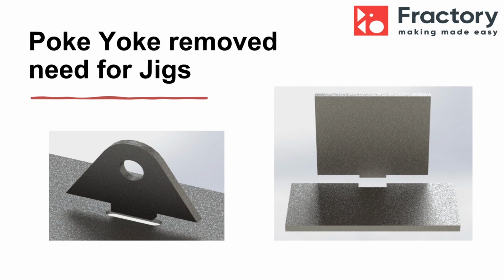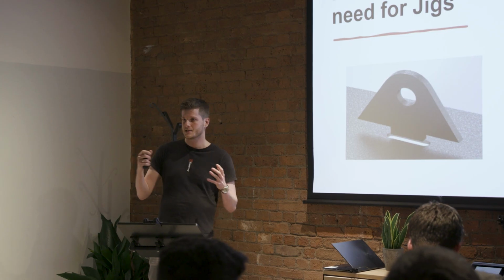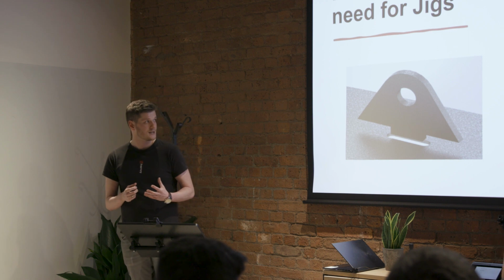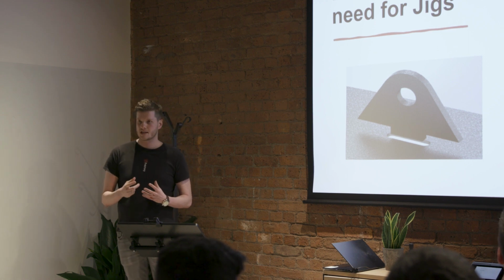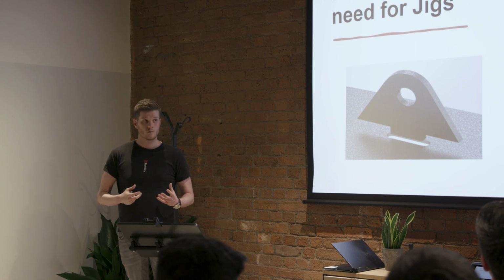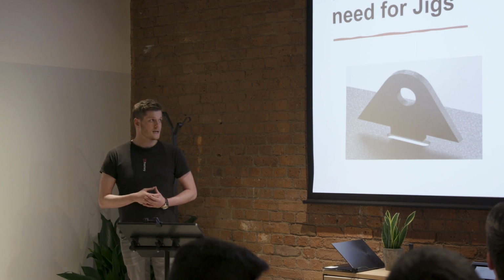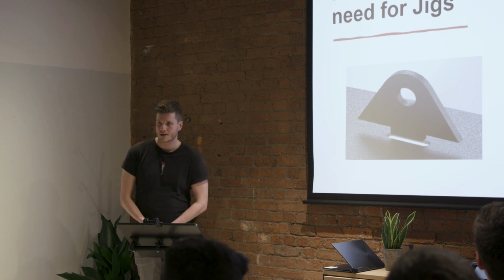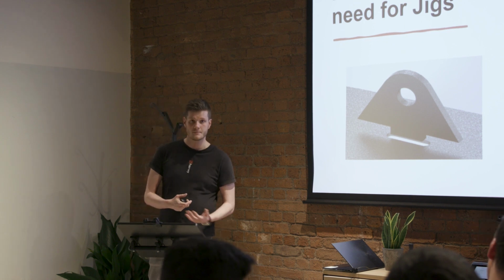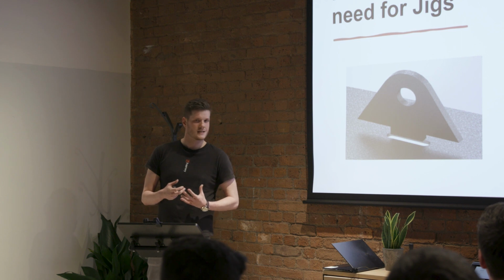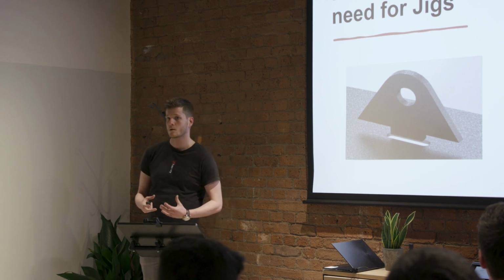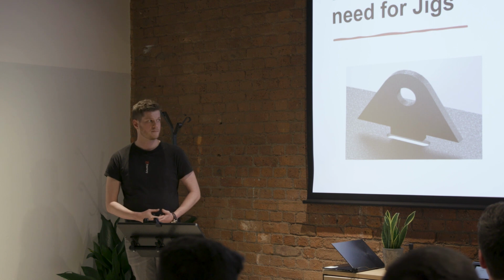One of my favourite words that I came across in engineering is the idea of poka-yoke when it comes to welding. So the poka-yoke is a very simple concept. You've got a tab on one piece, you've got an open slot on the other one. And these slot together prior to welding, and it just makes sure that the placement is all correct without the use of jigs, which also would have to be priced for. It means that the welders can move through your project a lot quicker, saving yourself time, and just gives you a lot more confidence and control over the quality of your own product whilst it's on the shop floor.